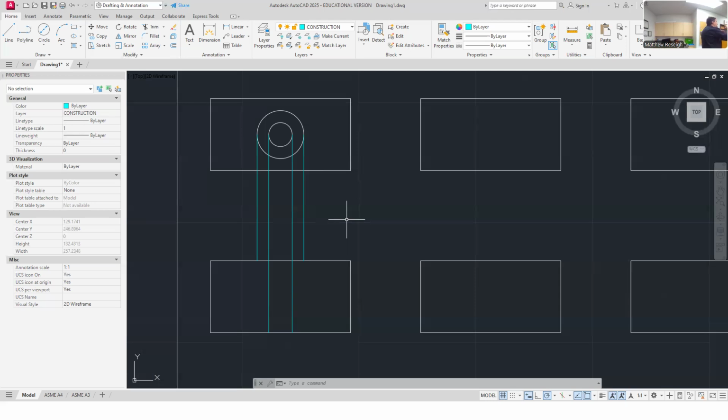There are applications where it's okay, but it's just going to be this big head sticking above the surface. So what we do, a lot of times when we use that type of fastener, we sink the head into the material, and we would have a machinist do a counterbore for us. And then my head would finish flush to the material surface. And you see this kind of configuration all the time.